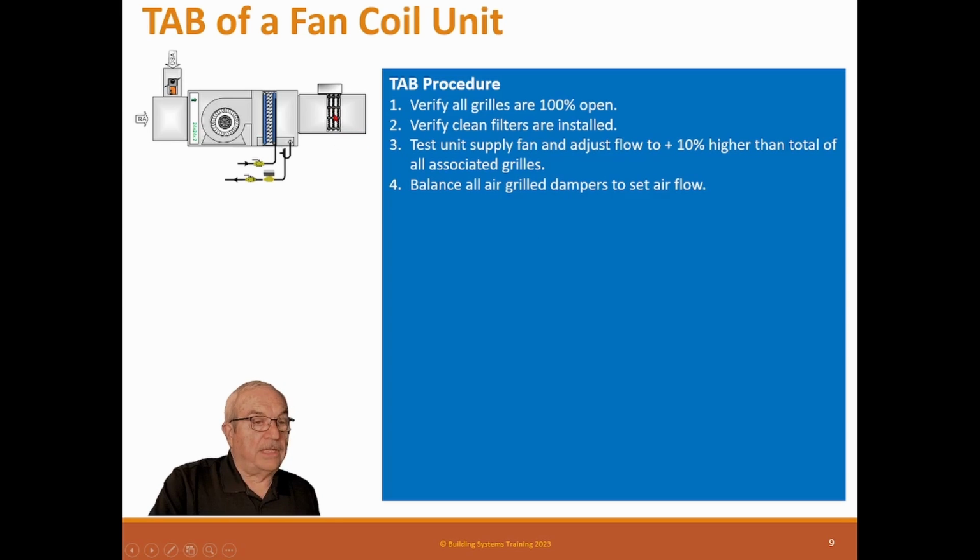You're going to turn the electric heater on and make sure the element actually heats air. It's really embarrassing when you turn in a report that everything works and you find out this heat strip has a blown fuse and it doesn't work at all. Well, you tested it. No, you need to make sure it actually works.